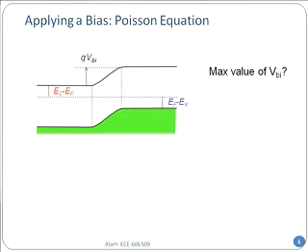Okay. Now, the next question: V_bi is the built-in potential in equilibrium. Now I want to apply a bias. The first rule for applying a bias is that you have to take any one of the materials in the device that you are interested in and ground it. Without grounding, you do not have a reference. So what you see on the right-hand side with a blue rectangle is my ground terminal. I'm going to ground the P side of the device.